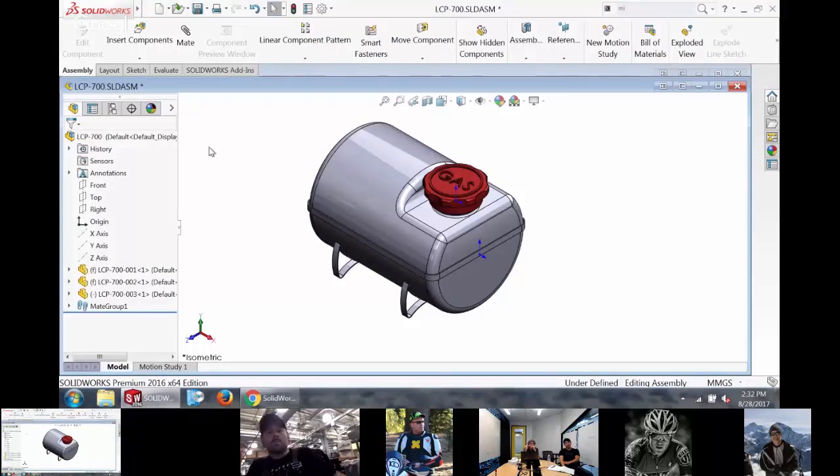But if it's a placeholder and you're still in the development side, give it a name. Just don't give it a really stupid basic name that somebody else might have used. You're going to run into problems like this. Also, when you go to put it in your vault, if somebody else has already used that, you won't even be able to check it in, because it'll be like, oh, there's already a part called cap. Sorry. So it's just, head that off at the pass.